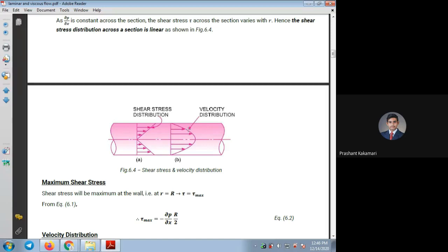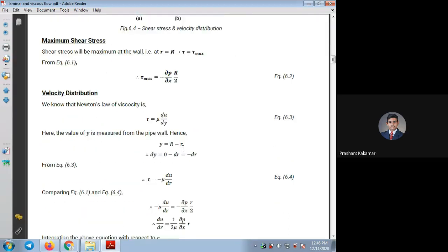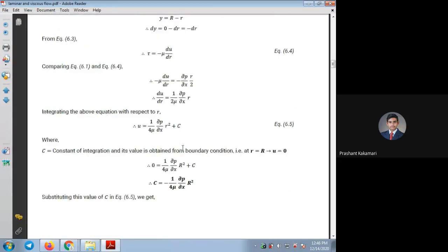Because we are finding the distance, always we are taking some velocity at the flow. But that velocity is not at the center or at the wall. Okay. So for the discharge value, if you are using the velocity term, that velocity is the average velocity. So for the entire cross-section area of this pipe, what is the average velocity here? Based on that, we are going to find the discharge. So for that, we want the average velocity.